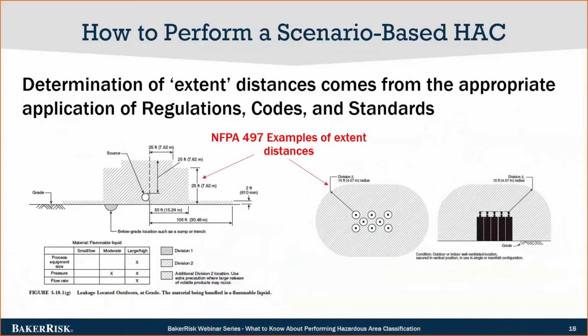After we've built the model and added in all of our sources, we can determine the extent distances based on the relevant code or standard that we're using for the study. So in this example, these two figures below are taken from NFPA 497 and show examples of extent distances for different types of equipment.